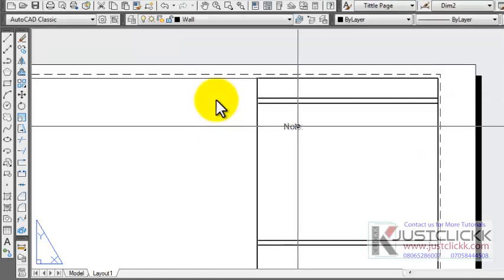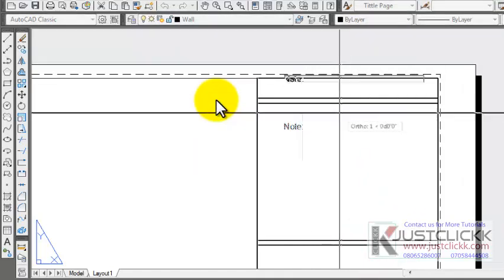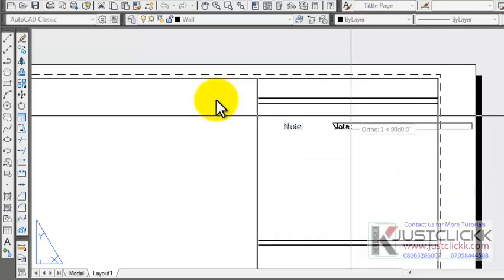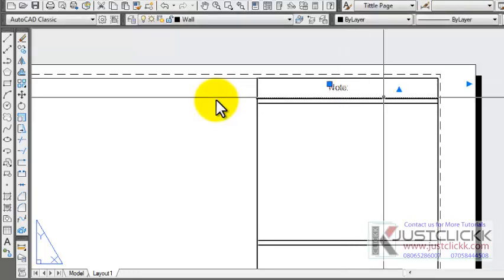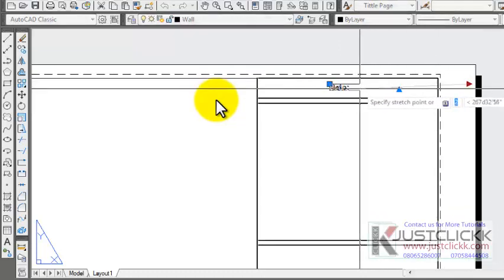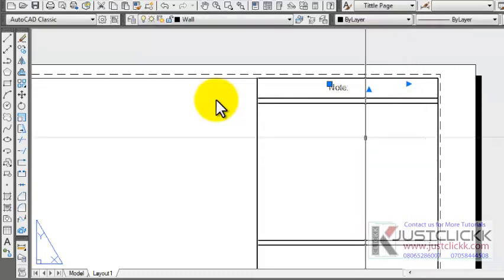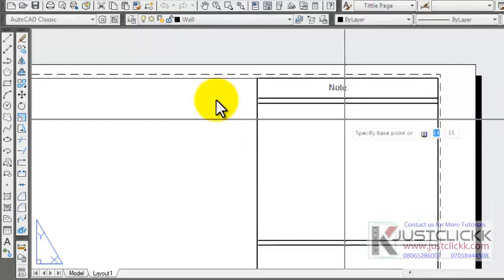So this is the text. You can move this text to place in the appropriate place. We have our auto on, so we can turn auto off by pressing the F8 key on our keyboard. So like so. If the text box placer is too long, we can reduce it like this. But if you're reducing this, that's okay. Then we can begin to copy this text.